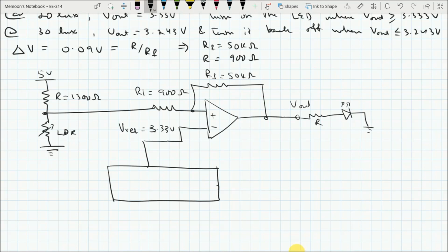So this is our digital to analog converter. Let's choose an 8-bit digital to analog converter with a Vref for DAC equal to 5 volts. Also we only have a 5 volt power supply, and we have 8 inputs. So this is your LSB, and this is your MSB.